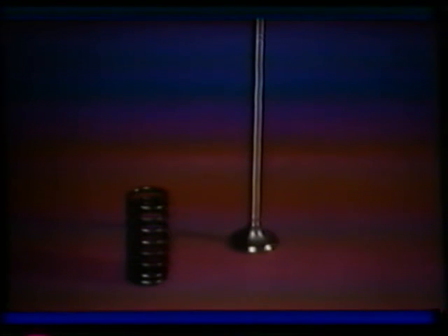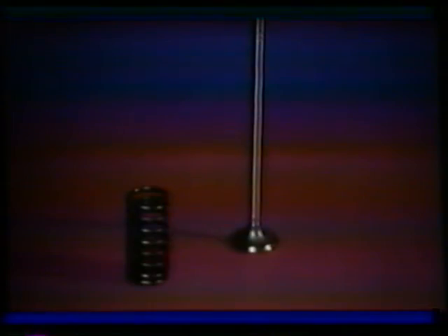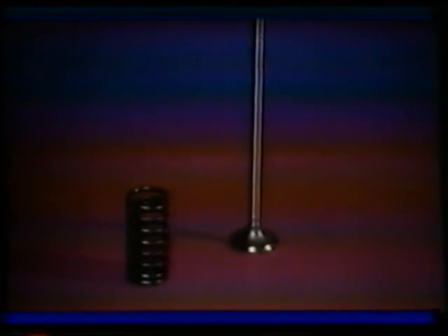The springs are made of extremely high-quality wire, and every inch used is inspected. An eddy current from a magnetic coil is run past the wire, and it detects any imperfections through the change in current characteristics. Any section of wire which has imperfections is automatically discarded. This is just another example of how details make the difference to Caterpillar.